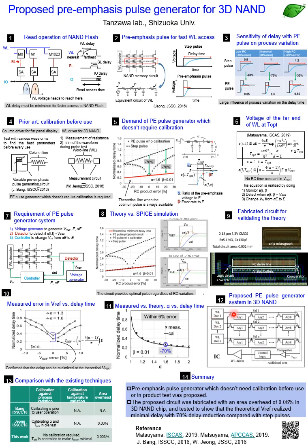This is one example of how you can implement this feedback system in an actual 3D NAND. In this example, each block is divided into 8 subblocks, array 1 through 8. If you access bottom line, for example number 2, then these switches simultaneously turn on.